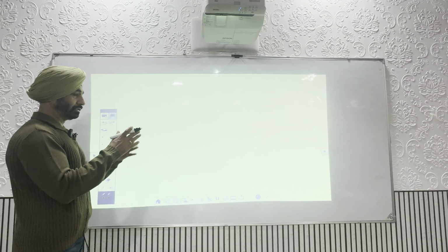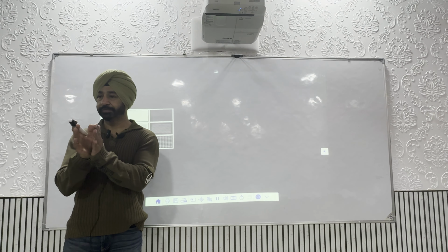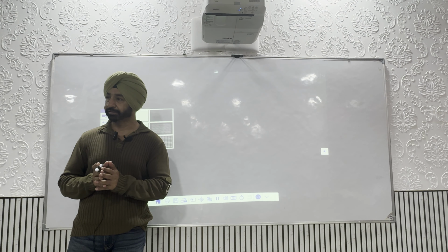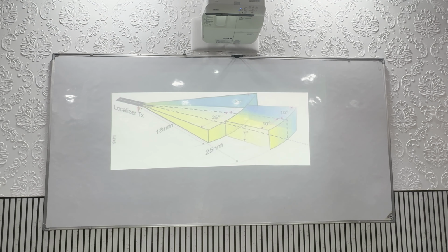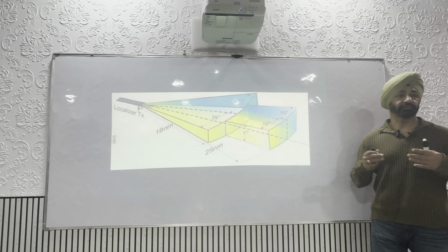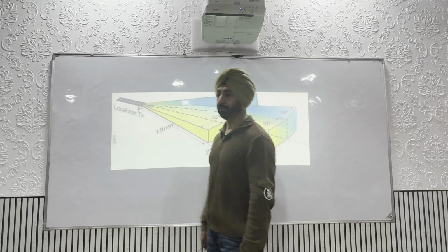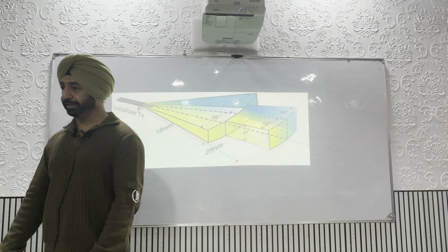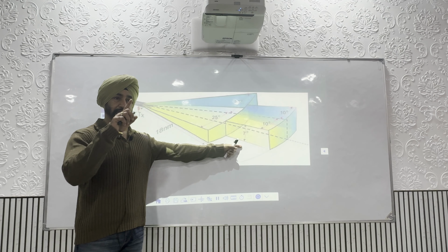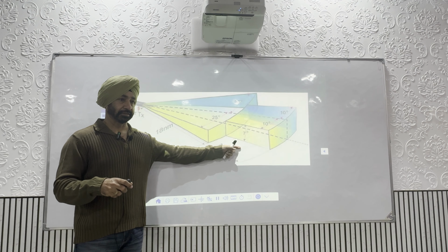Now obviously it is a beam, it is a cone, it is a directional transmitter, so it has got a coverage area. It is important because it is also asked in your exam. So horizontally, as the aircraft is far, this coverage area is less. As you keep coming closer, it will keep opening up. Your glide slope is 3 degree, so vertical coverage is up to 7 degree. So well above and below the glide slope, this signal is received.